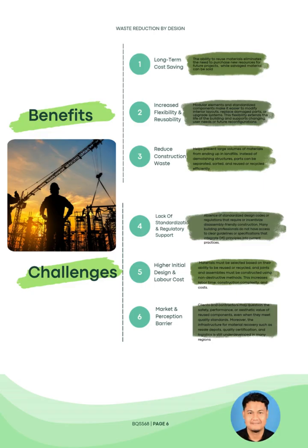Now, let's take a look at the benefits and challenges of DFD. Design for disassembly offers several important benefits. First, it helps reduce construction and demolition waste by allowing components to be reused rather than discarded. Second, it lowers the long-term cost by minimizing the need for new materials and reducing landfill fees. Finally, it supports flexible and adaptable building designs which can change over time without needing full demolition. Overall, DFD encourages a circular economy approach in the construction industry.